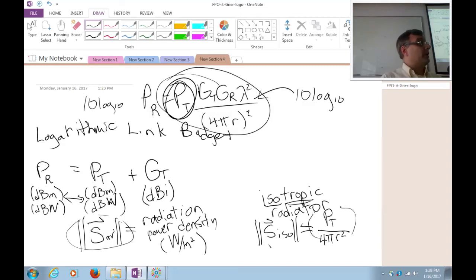It's on a printed circuit board, which means it's got a ground plane and some FR4 dielectric material underneath it. That FR4 dielectric material, especially when you get up to upper UHF and microwave frequencies, starts to get lossy, and you can burn up energy on that, so that the power that you put in doesn't all make it out into radiated waves. So that's an important concept in antenna engineering, the difference between